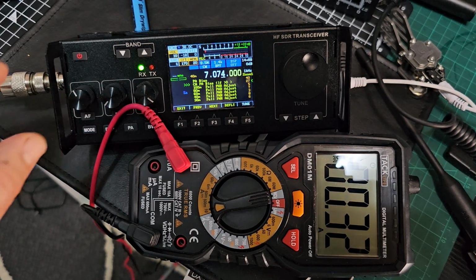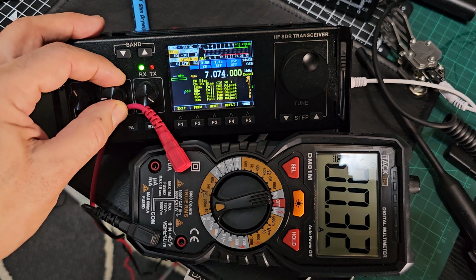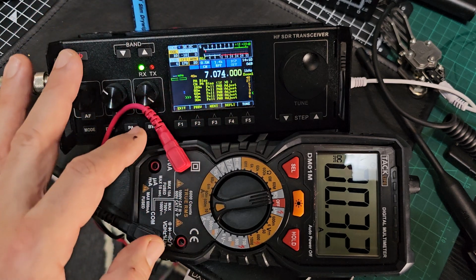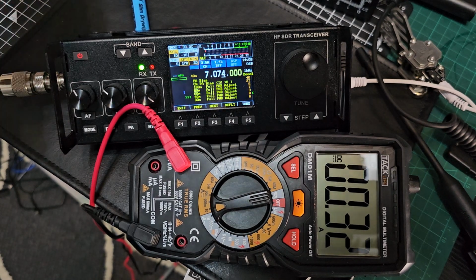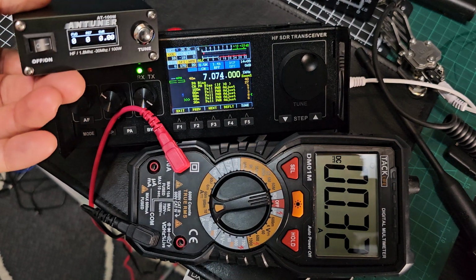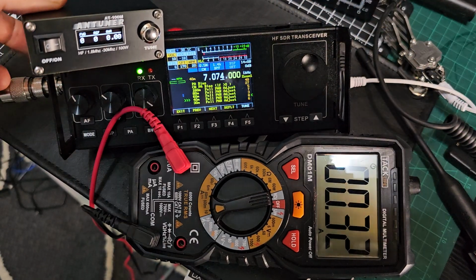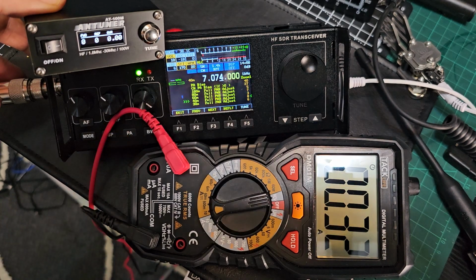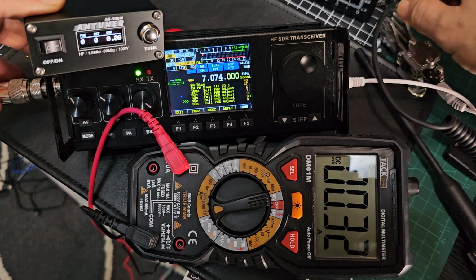And that's it really. Now, if you want to start setting the power adjust, so let's say you went to 40 meters and you transmit on 40 meters, just connect any watt meter, you know, transmit. So we've got our tuner here. It is on a dummy load. And if we transmit now, we want it on 5 watts. So we just change PA to 5 watts. We're still on CW, and we'll transmit. We should see 5 watts there.